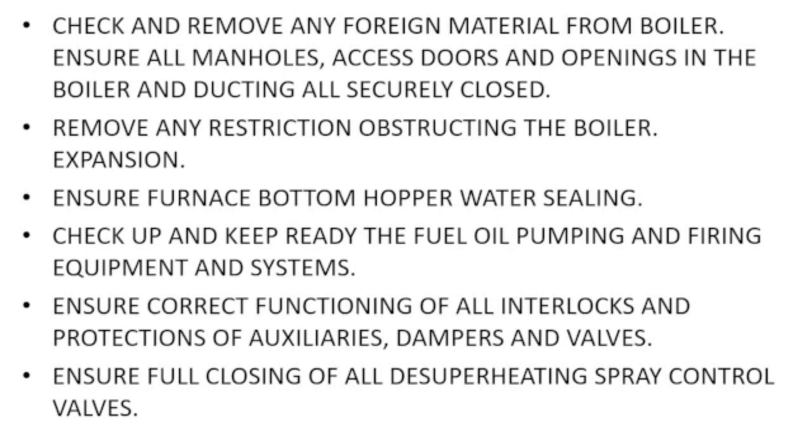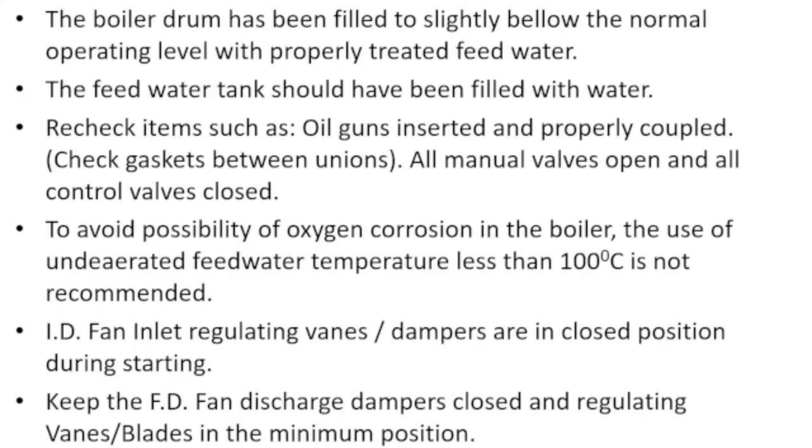Check up and keep ready the fuel oil pumping and firing equipments and systems. Ensure correct functioning of all interlocks and protections of auxiliaries, dampers and valves. Ensure full closing of all desuperheating spray control valves. The boiler drum has been filled to slightly below normal operating level with properly treated feed water. The feed water tank should have been filled with water.